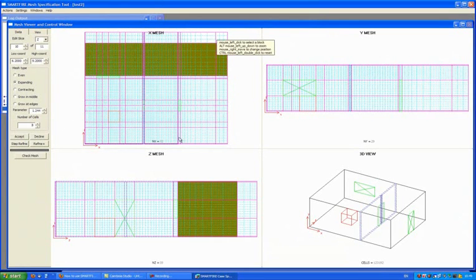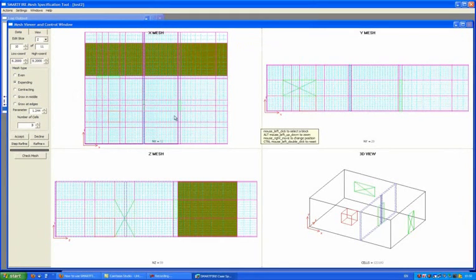It's always worth considering the quality of the mesh and watching for very long, thin, narrow cells or very small cells adjacent to very large cells, because these may have a negative impact on the quality of the simulation that you produce. So always be aware of the quality of the mesh when you're going through this stage, and do question the mesh that is created automatically, because the meshing rules do not always perform optimally when there are certain complexities in the geometry.